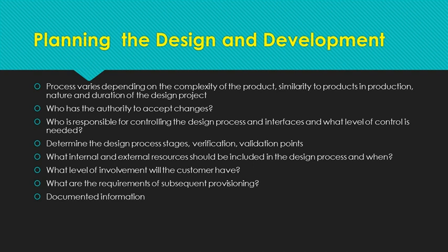Who will be responsible for the project and address issues of interface between the project members? Typically, this is the person titled Project Manager, and this person calls for the design reviews and follows up on promised delivery dates. At what point in the design will the design reviews occur, and who will participate in them? Manufacturing and quality should provide information as to similar processes and issues. If processes are being outsourced, the outsourced provider should be included to prevent issues increasing cost or lead times.